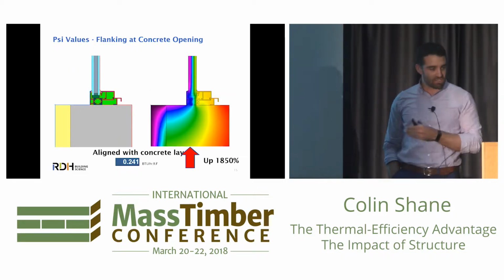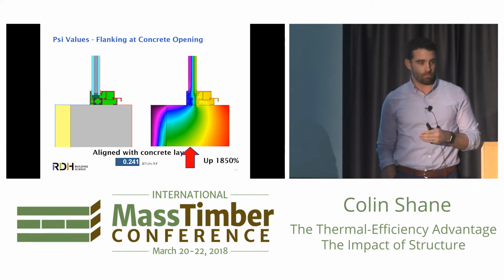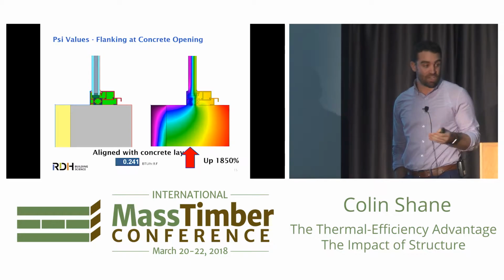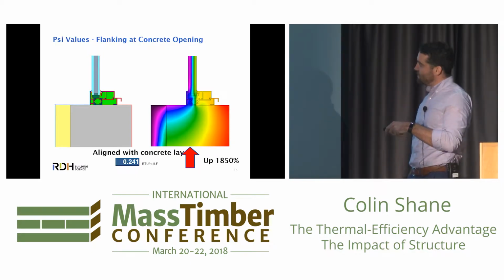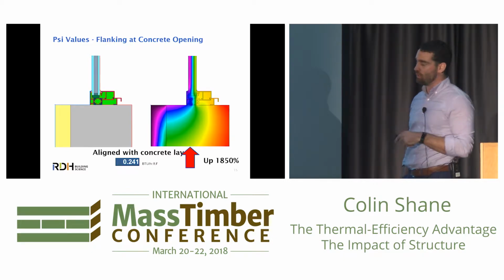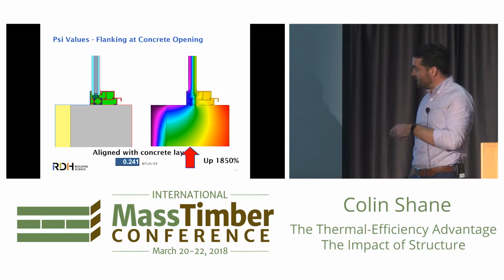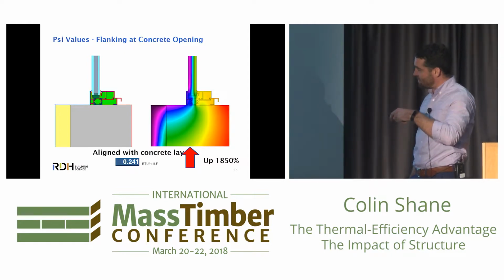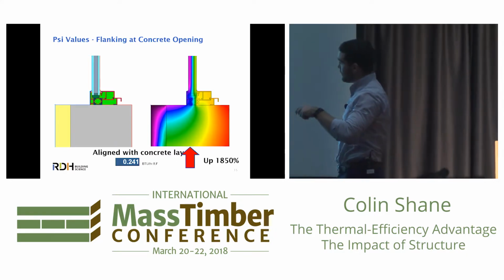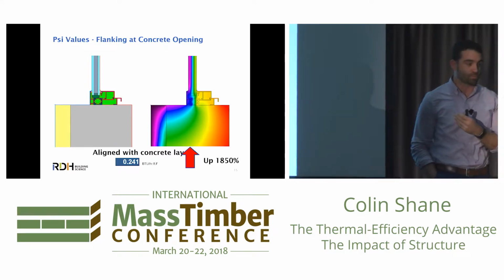Now, maybe we want to recess that window a bit into the concrete opening, right? So again, this might be something we would commonly do architecturally or aesthetically, but now because this insulation here isn't lined up with the insulative portion of the window, that thermal flanking that happens, that heat loss that's going to basically bypass the insulation of these 2 assemblies across that path there, shoots the linear transmittance of this detail up by huge percentages, okay?